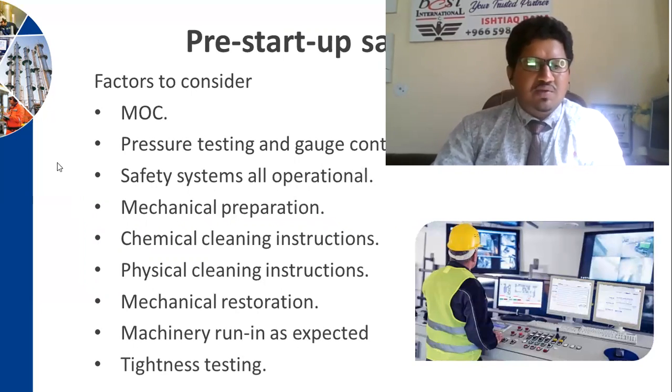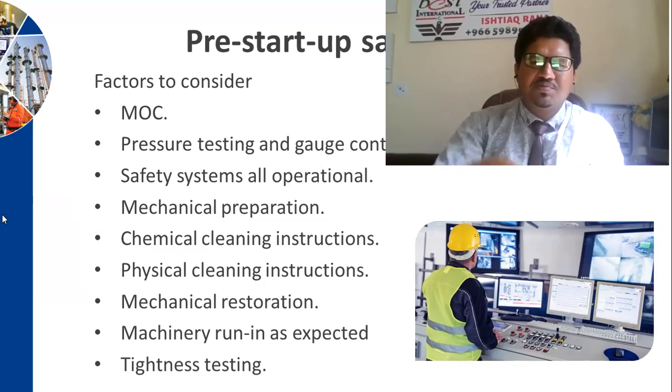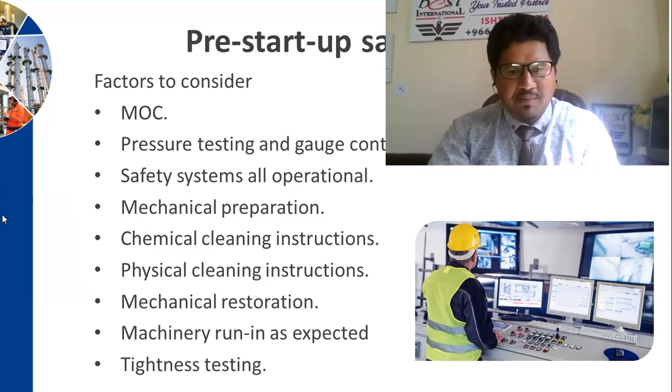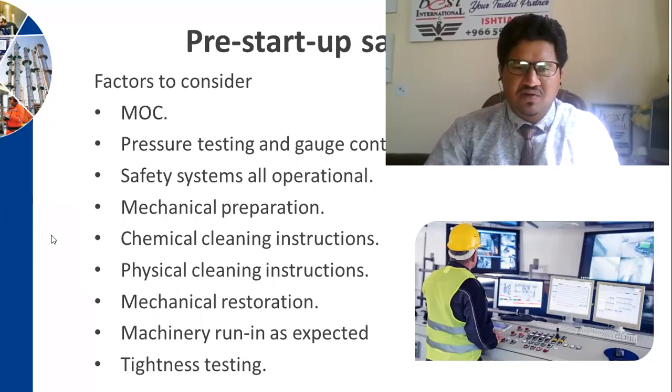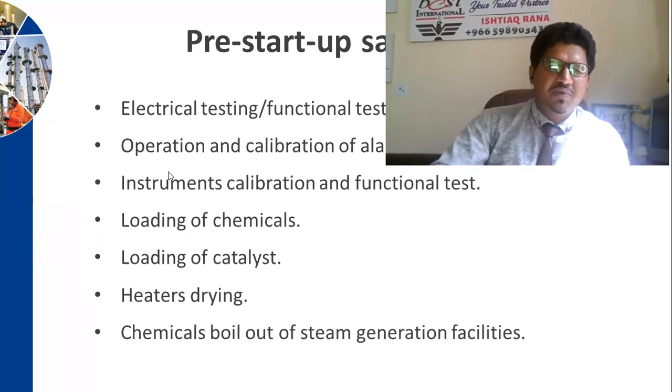Pre-startup safety review is very much important. What factors do you need to consider? MOC, management of change, pressure testing, and gauge control settings. Safety systems all operational, mechanical preparation, chemical cleaning instructions, physical cleaning instructions, mechanical restoration, mechanical run as expected, tightness testing. So these are some of the pre-startup safety reviews that must be done, and these are the important factors to consider.